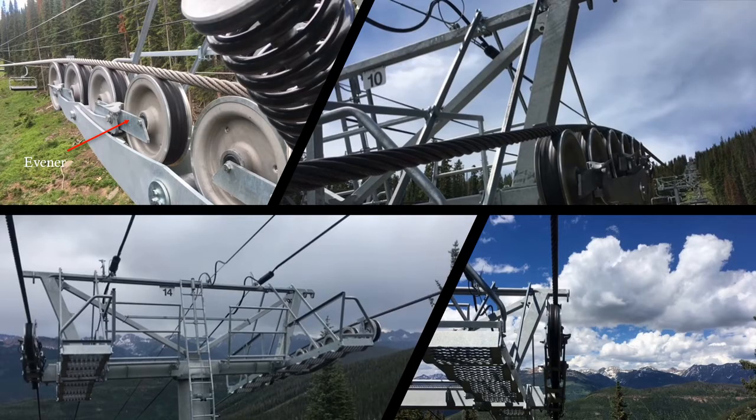These are some images of shiv assemblies from up close. In the image on the top left, note how the evener feeds into an intermediate bracket which feeds into the main frame. This is commonly used on shiv assemblies with a larger number of shivs. In the image on the top right, note how all of the shivs have a grooved rubber liner that the haul rope sits in and runs in. This liner will wear out normally over time as the ropeway is used, and is the reason why shivs on ropeways need to be replaced in what is called line work.